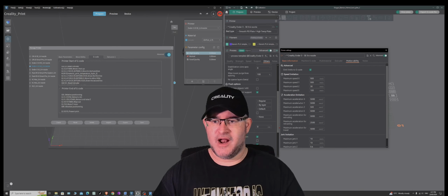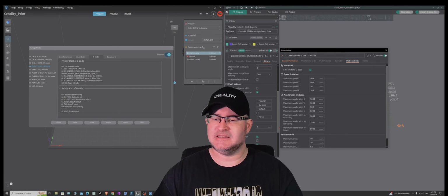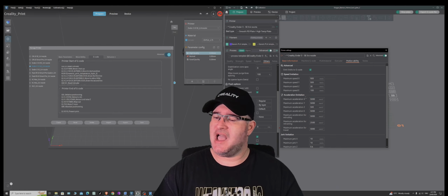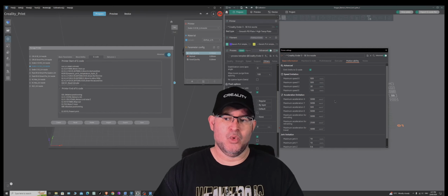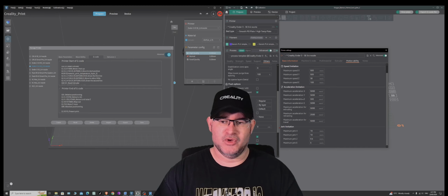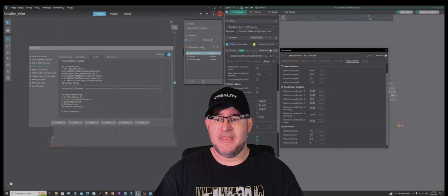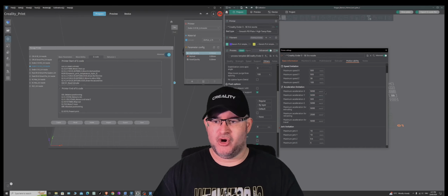So for us, luckily enough, Orca Slicer recognized the SE because it has a profile. But if it didn't have a profile preset in Orca Slicer and you added your printer manually, all these acceleration points would be set at the standard value, which is generally either 1500 or 500 for your acceleration on your XY, sorry, and your E. And then obviously your max speeds would need to be changed as well. So you just need to make sure you correlate with that.